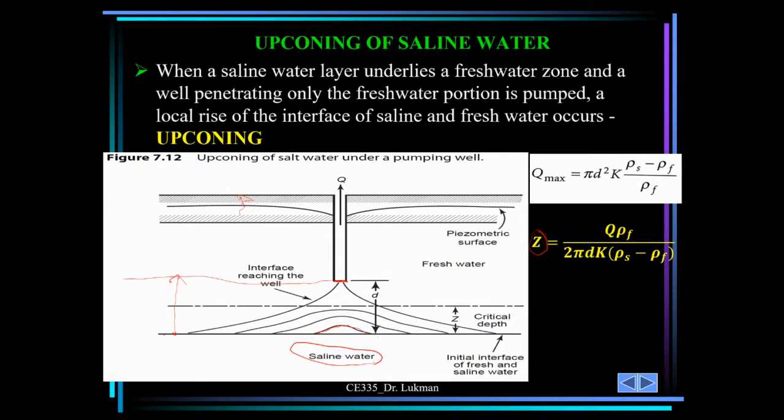So you are distorting the balance, the equilibrium, and more of the saline water will try to maintain the same equilibrium, because you are removing the fresh water. Unless of course it is counterbalanced by a particular recharge area where you have the fresh water being injected. Otherwise, in the absence of any input, the saline water will expand to maintain the equilibrium, thereby moving the interface gradually.